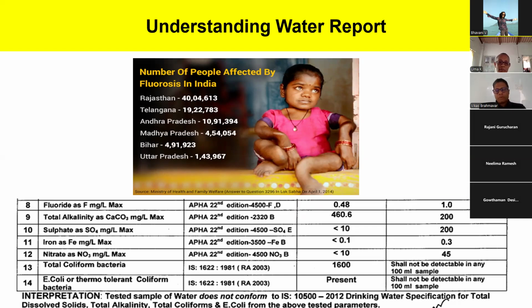The water will still look clear if you have fluoride in it. If you boil the water, fluoride doesn't go. So these are contaminants which are there in the water, and we have to test it to know these values. It won't be present in most cases, but once it starts in a particular region, it's generally there for a long time. It will keep coming. If it is in the 3 ppm, 4 ppm range, which is 4 milligrams per liter, generally in that area there will always be fluoride, for the next 10 years.